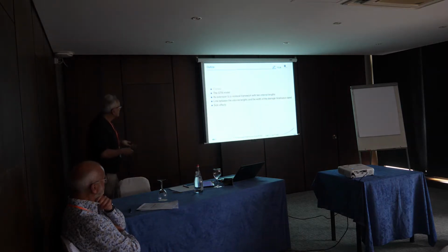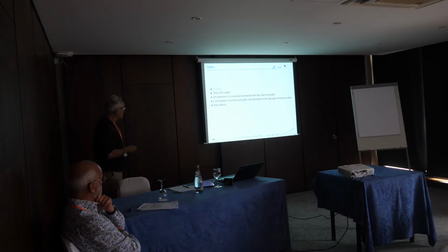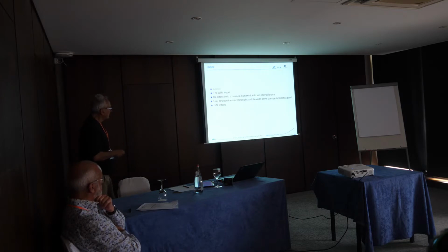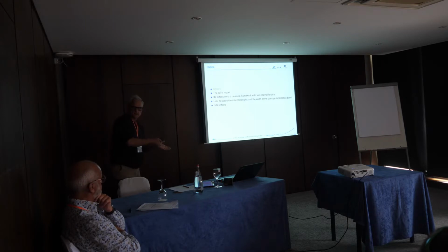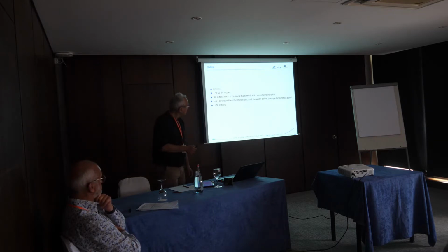So after this context, here's the outline of my talk. I will briefly present the Besson-Needleman model, which I think is very well known, then present its extension to a non-local framework using two internal lengths. And then we will use this model to see the link between the internal lengths and the localization bands we observe in the simulation, and investigate some size effects.